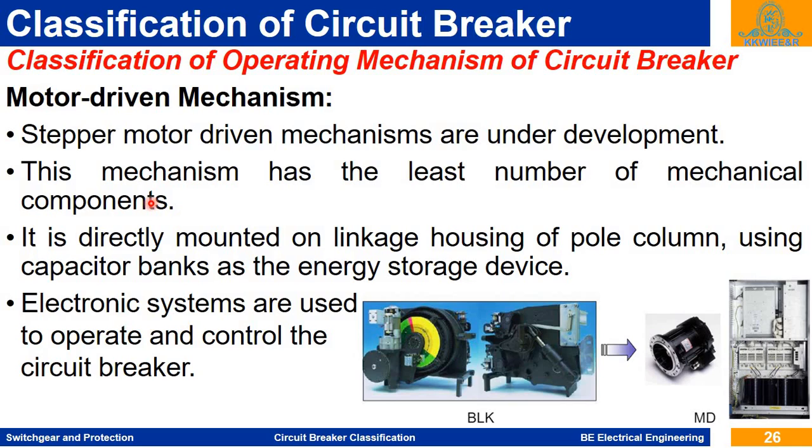So that maintenance of mechanical components is reduced by this motor driven mechanism. It is directly mounted on the linkage housing of a pole column, using the capacitor bank as the energy storage device.